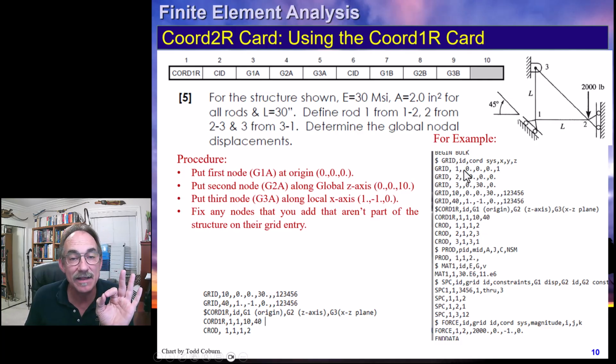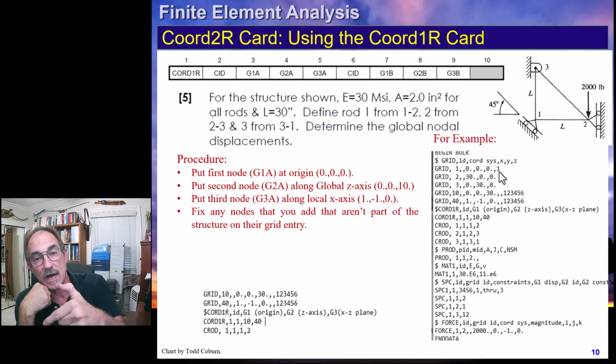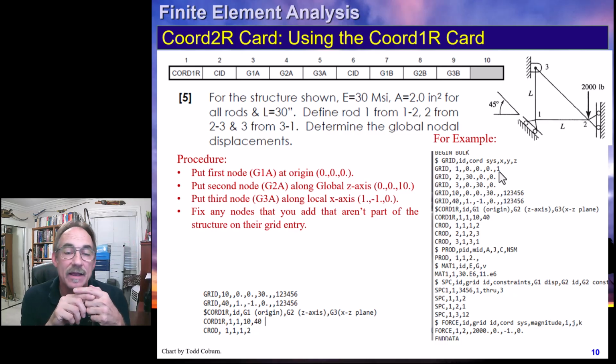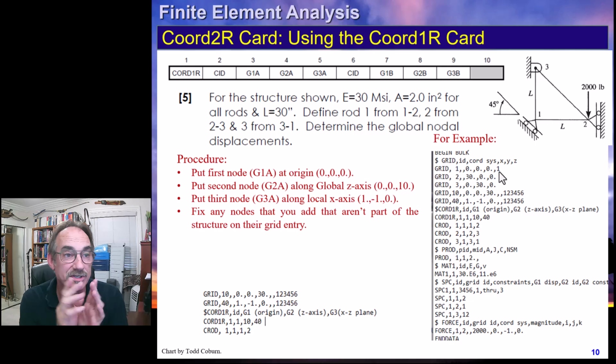Now look, we're identifying that point in the global system, but we want any output and deflections in that local coordinate 1 system. Now the output will show, if we show an x deflection at node 1, it will actually mean positive down along the incline. A negative x deflection will be upwards along the incline. A positive force in the y will mean we have a reaction pushing up perpendicular to that surface. And a positive in the x would be wrong, it means something's wrong, because that roller means you're not going to transfer any forces. So that's how it works.